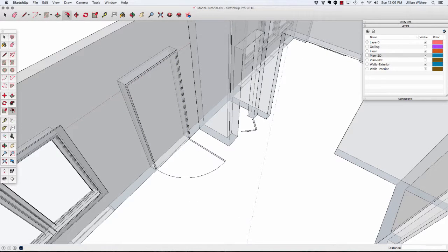Click on your offset tool. We are going to offset the face by 6 inches. So that's going to be the outline for our recessed panel. And then I want to have, usually in a recessed panel door, the bottom has a larger reveal than the top and the sides. So I'm just going to click on that bottom edge and I'm going to drag up.